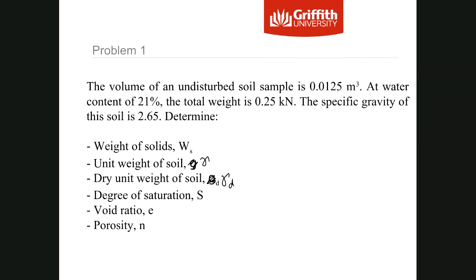So I already talked about density, right? Something that you really know, density. For soil, it's usually 1.5 to 1.8 grams per cubic centimeter. This would be a good range for most soils. If you get something much higher, this means that you made a mistake and there is something wrong. Density, we use it in science very often, but in soil mechanics, we're not going to use density. We're going to use unit weight.